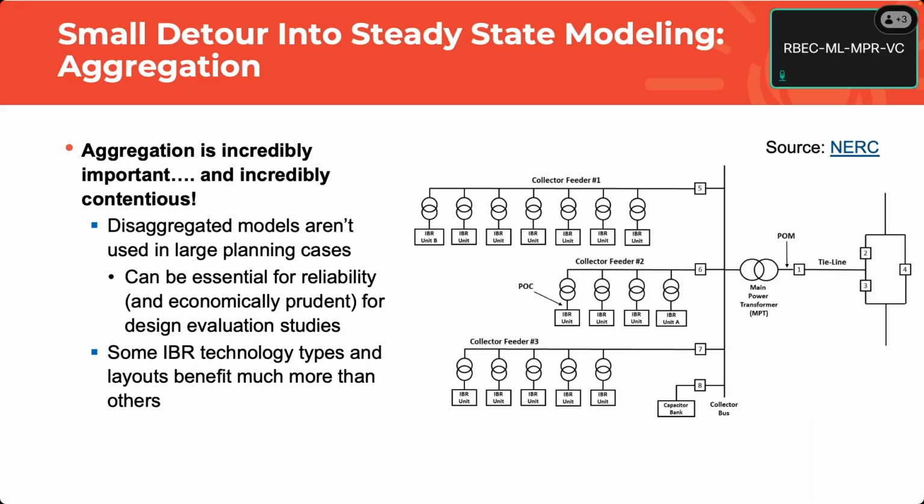You're doing a study case, and the Eastern Interconnection is every machine, every piece of equipment, every element in the case. When we were putting together the system-wide cases, we would actually delete a lot of things, turning them off to get rid of buses in the software because we were up against the limit. That means if we're up against the limit with aggregated models only, we're certainly not going to be able to do each of the IBR plants in their entirety. Because now instead of 10 elements at an aggregated plant, we have hundreds, maybe 200 or so, buses and elements in an actual disaggregated plant.